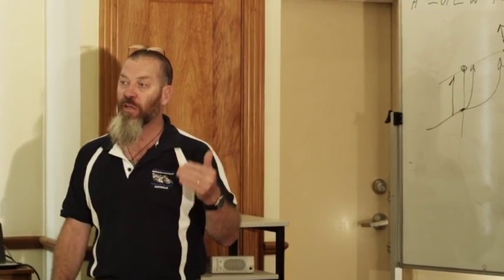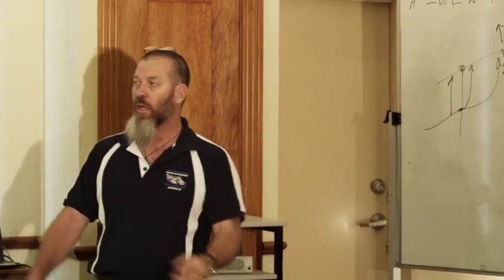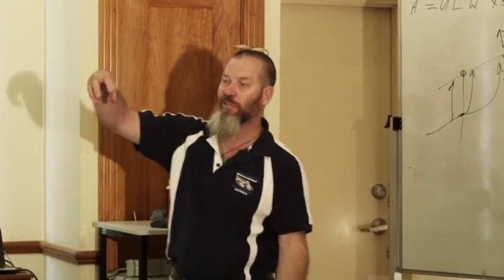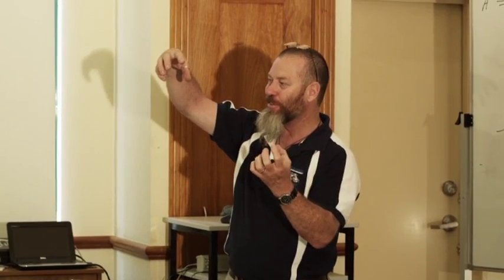But if you're doing an N2 tiled roof or N3 tiled roof, you'll be lucky to come up with 1 kilonewton of resistance. So if you think about kilonewtons being hundreds of dollars, we'll say 1 kilonewton equals $100. I've calculated that I need a $100 connection, 1 kilonewton. I'm going to turn around and put a $290 connection where I only need $100.